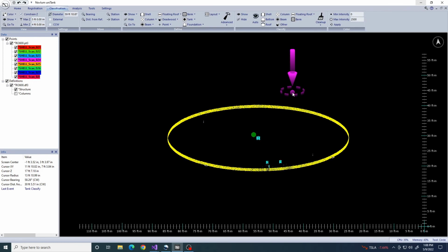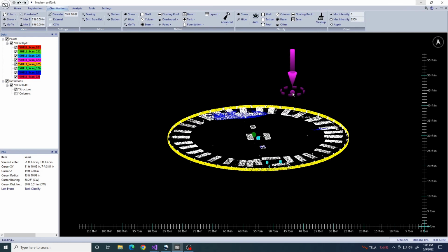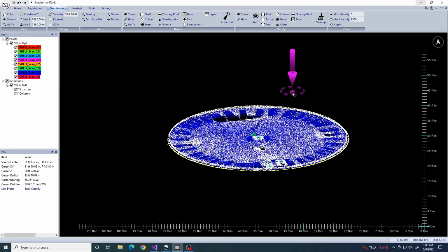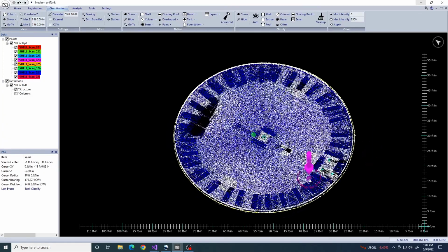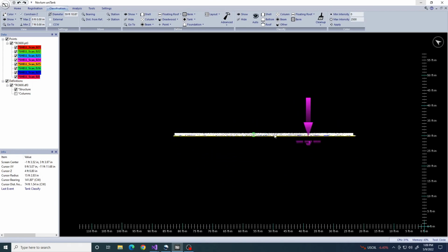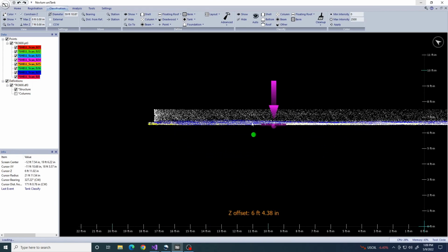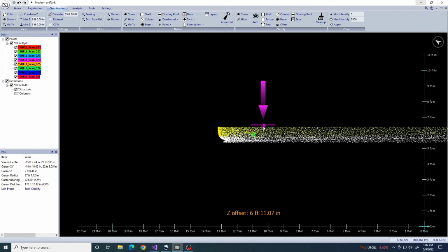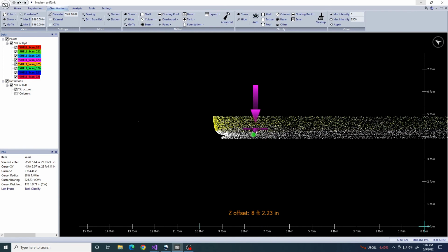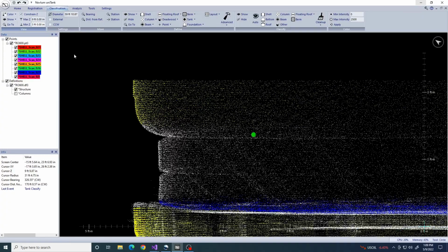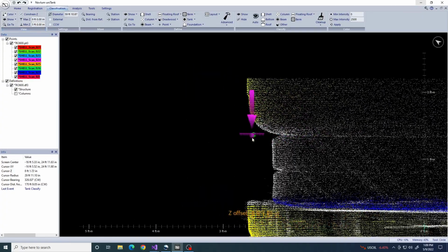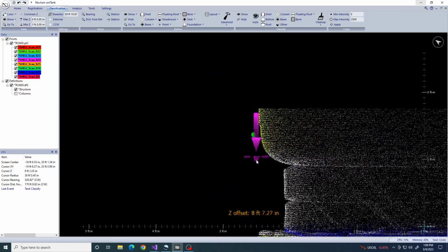Once the tank has been classified, you can see that the top side of the floating roof has been correctly identified. Before we do the rim space analysis, we want to reclassify some of the shell points near the floating roof seals. These transition areas are not clearly visible and will create discontinuities in both the shell and rim space analysis. Where you will see it most is in the banding analysis.